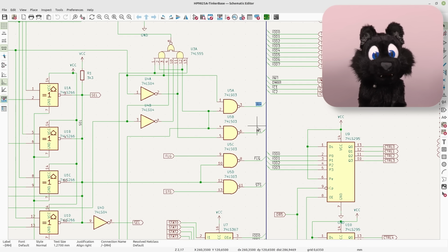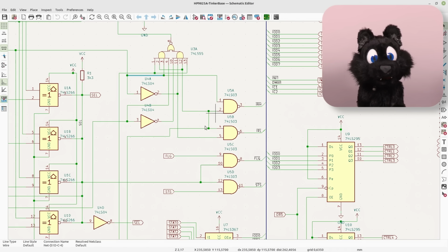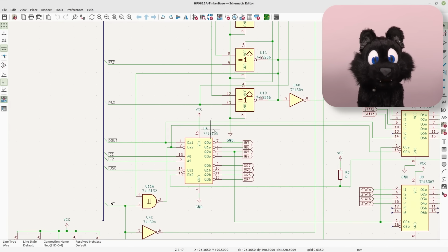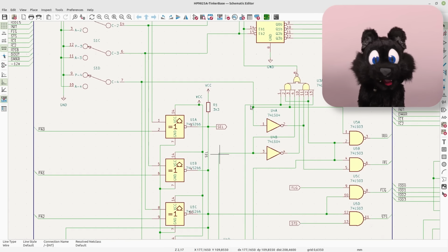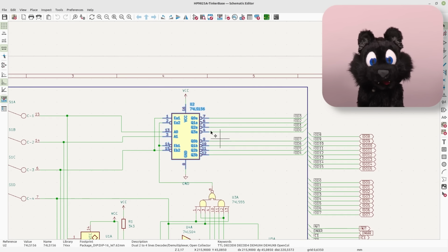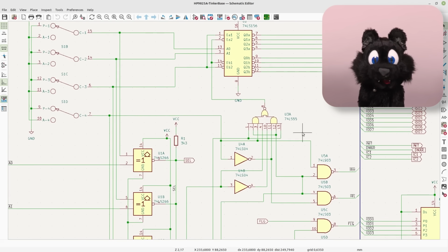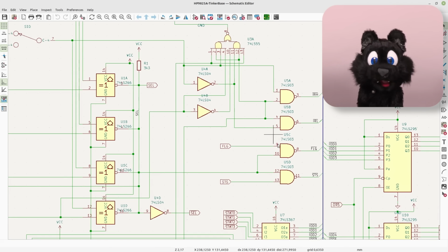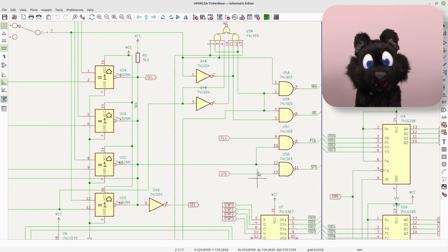If the card wants to interrupt the CPU, it sets the request line, either the high or low priority one, depending on the I/O address. After that, the CPU will interrogate the cards and ask for the matching data line to be pulled low. That way, the CPU can find the highest priority device, even if all of them request an interrupt at the same time. All of this has to be baked into the addressing circuitry. Check. Flag and status lines are to be set whenever the card is selected.